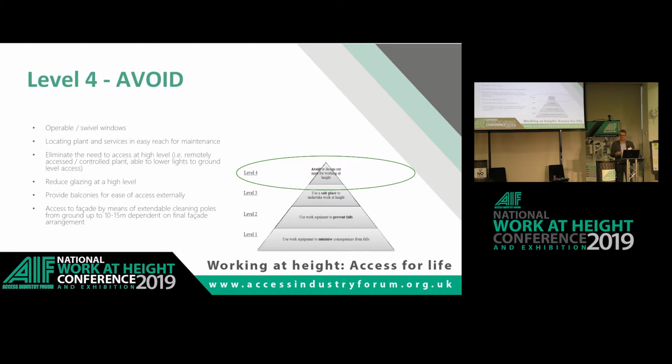So we worked with the architect and said, well, look, we're going to redesign the top part of this building, the top 4 floors, and we're going to take the glazing out, and we're going to put something in that looks very similar to glazing. From the ground, you won't notice the difference. But actually, you probably only need to clean it maybe once every 3 years, rather than all the time. If you're cleaning an external facade of a building, you're going to do that maybe 4 times a year if you're doing it properly. So you reduce that frequency quite dramatically by using other materials or reducing glazing wherever possible.